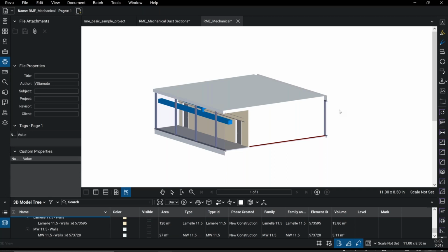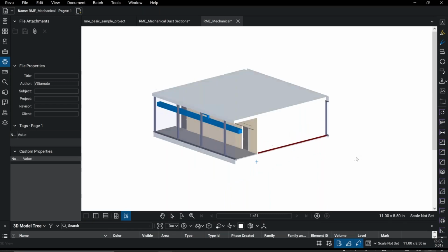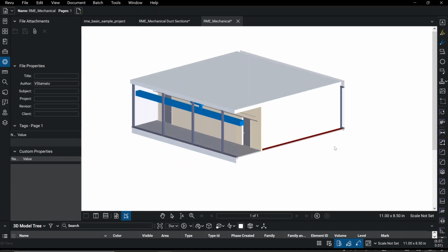All right. We have another question. Besides opening IFC or U3D files, which are created from other 3D software, can Bluebeam create 3D models from scratch? At this time, that's not something Bluebeam can do from a 2D PDF. You cannot do that from scratch. It won't generate a 3D view for you, but it does work importing it in through other file formats. So it essentially needs to be an IFC or a U3D. Good question, though.